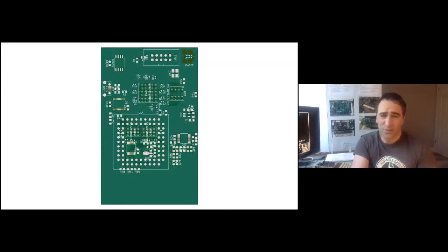It's been ages and ages working through all the buffers. The big problem with this board was that something like half the board would have been covered in buffers if I was using normal sized buffer chips. But I found these tiny little BGA buffers. They were the 74LVT162245. I was excited about LVT. LVT seemed fast and 5-volt tolerant, and it has 22 ohm resistors on its outputs, which terminates things a little and should hopefully make the high-speed signals from the FPGA a little more palatable to the slower logic on the outside.